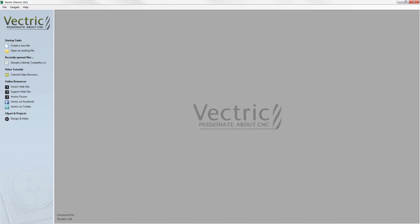So we're going to look at opening a new file where we'll import vectors that have been created in the Cabinet Maker's software to demonstrate how we'd apply the toolpath template to future jobs. So we're going to demonstrate how we'd go about creating a new file with all the exported vectors that we've created in the cabinet design software. Now, some cabinet packages may have the option to export the vectors as DXF files, and others may export each individual vector as a DXF.